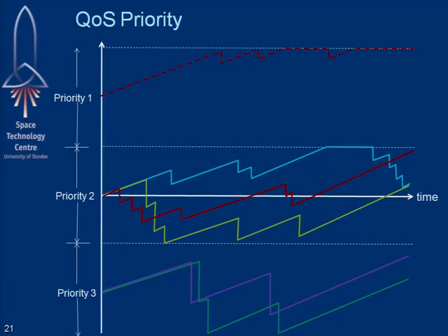We can also detect that somebody's hit or staying at this lower limit as well, and we can report that as an error. This is actually babbling idiot protection. So if somebody hits this lower level, they've actually used much more than their credit, so we can signal this as a babbling idiot detection.